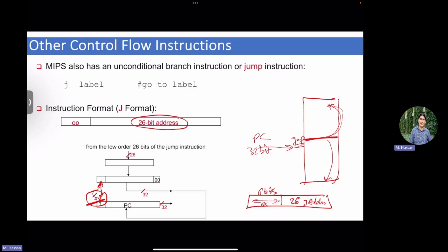Each address is 4 bytes. Your memory is byte addressable, so every address is in fact 1 byte. But what is the 4 bytes? Your instruction, right? So that's exactly the reason. Here, I'm not jumping anywhere in memory. I cannot jump in the middle of an instruction, right? So your step for jumping is in fact an instruction width, right? Which is 4 bytes. True?